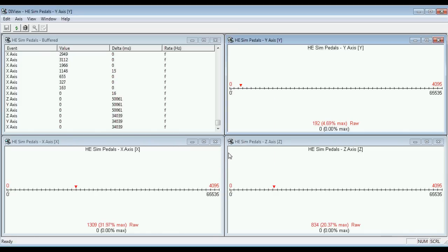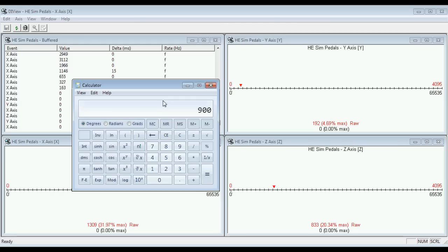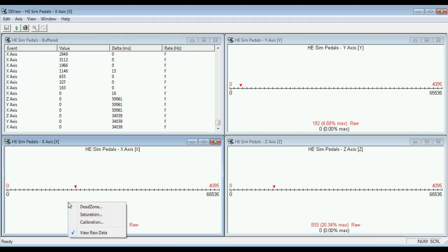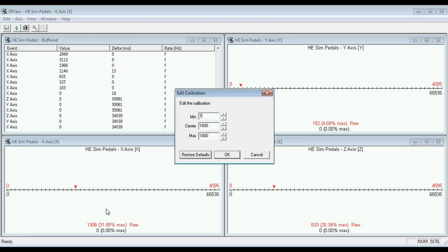Alright. Clutch, I don't want the full range, I want the dead zone to be smaller. So I'll use something like 1500 and then to about 1900, I think. So 1500 plus 1900 divided by 2 gives us the average. Calibration: 1500, 1700, 1900.